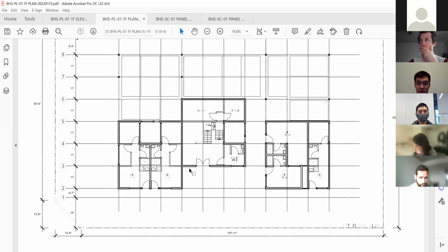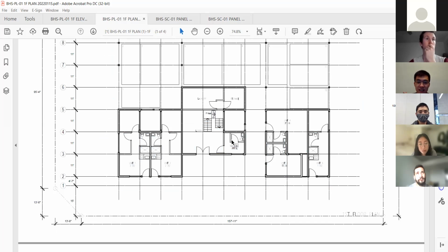So for these thicker walls, we intended all of these to be structural, with a thickness of 8 inches, but I don't know if that's common or not. So it's totally free, that could change. Yeah, but I think 2 by 6 should be good enough. You can leave it as a 2 by 6 stud wall for now. Okay.